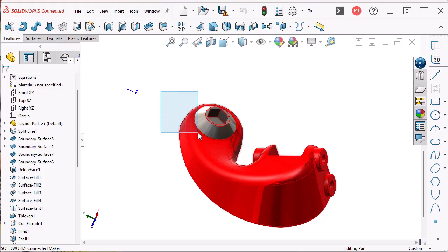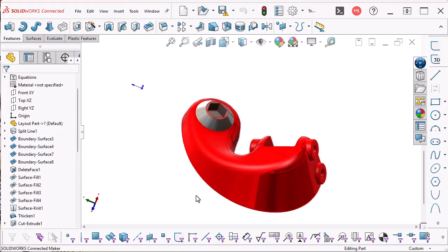If you make a box, you're going to select all of the edges within that box, and you can use the selection filter. This is F5. It usually comes up at the bottom, but it can show up in other places. Some of these selections have hotkeys. Filter vertices is V, filter edges is E, filter faces is X. You can make some of your own if you use the selection filter quite often. Hotkeys, especially within sketches, can be very effective. And the invert selection option is also overlooked quite often.